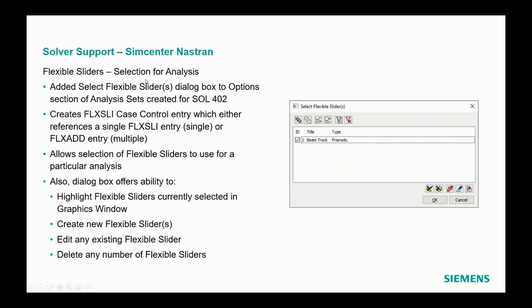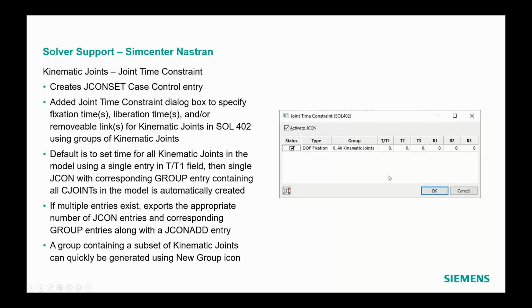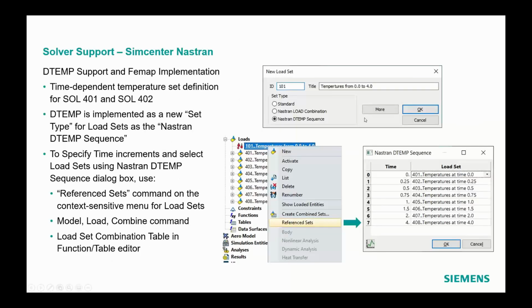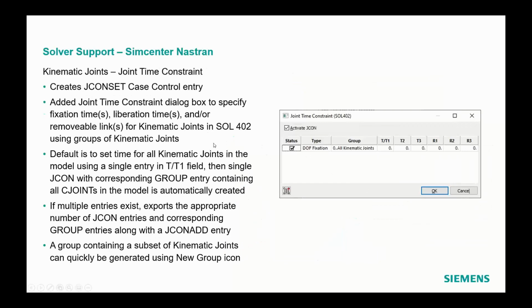And then obviously they've added solver support for flexible sliders. If you are using these, I think you do have to go into the analysis set and activate it. But this is a manager for that. And then obviously the same thing for the kinematic joints. You have to go and check it in the analysis set to make sure that it's included. Kind of the same thing for monitor points if you've ever had to deal with that.